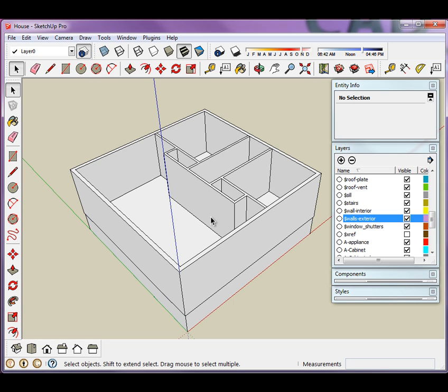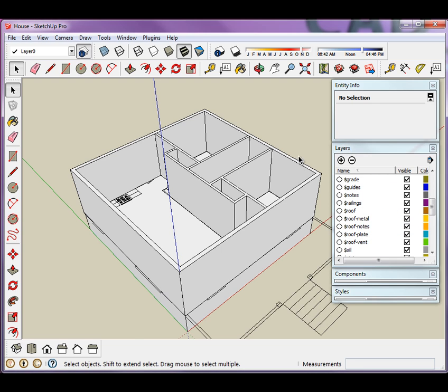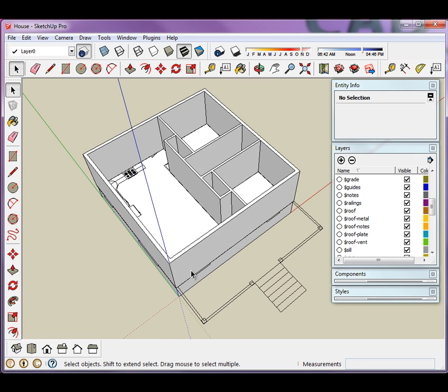But let's say if you wanted to, before you start building the rest of the doors and windows, go ahead and build the roof, right? The complete envelope. And then we could start penetrating the envelope. So, for example, in this case, if you recall, we've got a porch that sticks out. Let's turn on that XREF again. Now here, what we want to take a look at is the extent of the roof, right? And at this point, we might need to see our roof layer.